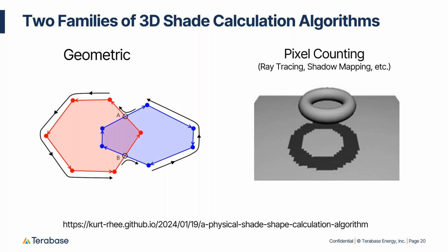The first family that people are probably most familiar with is the geometric family. That gives you a 3D representation of a site with vertexes. So you have an XYZ point that's representative of an edge of your module or bay, and four of those points create some polygon that represents your tracker geometry.